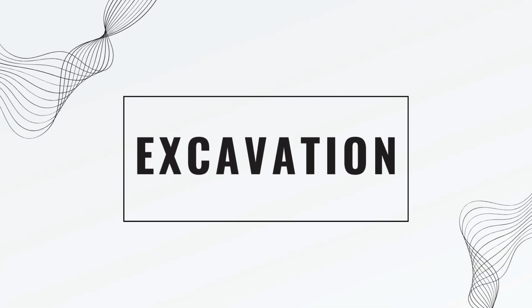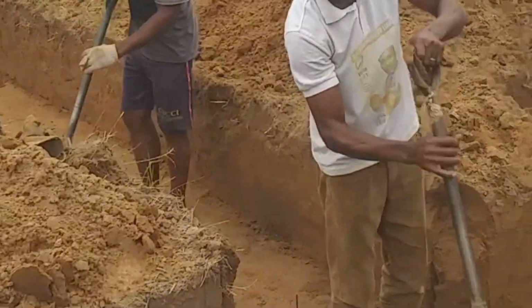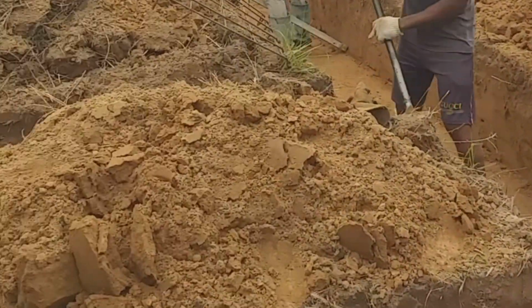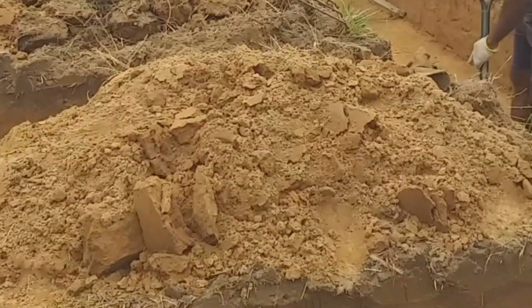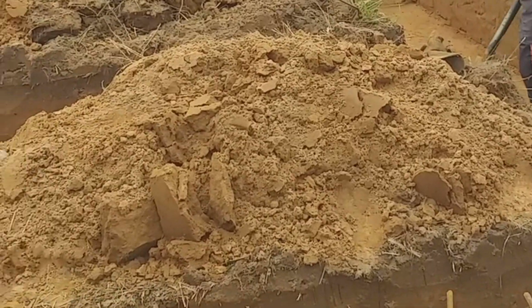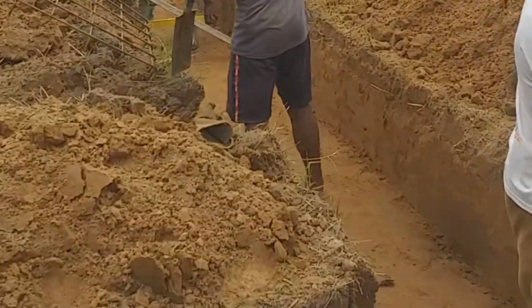The excavation stage. Yes, and when you talk about excavation, this is a process which involves the removal of the topsoil, which could be any vegetative or decaying matter, which could make the soil compressible and therefore unsuitable for bearing structural loads.